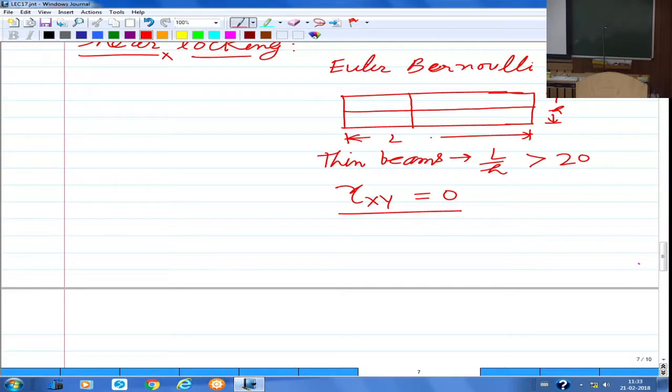Of course, when you are holding all the papers together, the bending stiffness itself is higher, but what I wanted to demonstrate is that if you have a thick beam, then the total deflection has a contribution from bending as well as the transverse shear deformation. So if you use a finite element which does not allow transverse shear deformation, then the deflection is going to be under predicted. That means whatever you simulate from finite element using Euler-Bernoulli beam theory would be much less than what you actually get. So that is what would happen if you use Euler-Bernoulli beam theory for thick beams.